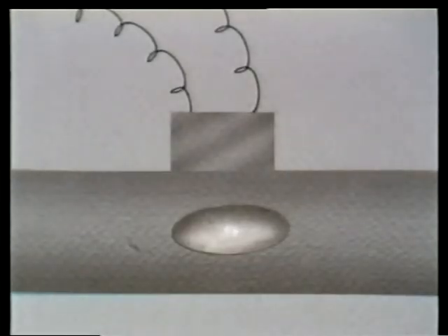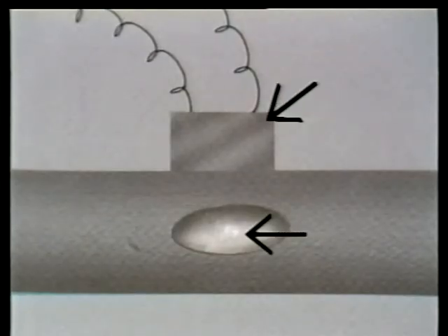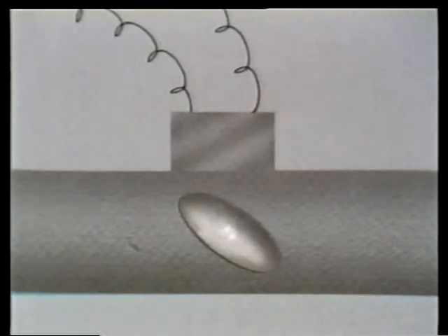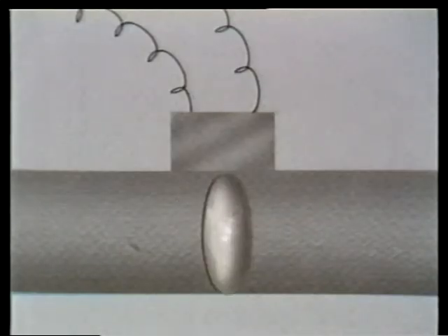The inlet air throttle is a butterfly valve within the inlet piping. The control unit up above receives a signal from the motor when it starts to draw too much current. The unit then partially closes the butterfly valve, restricting the intake airflow. If demand is still too great, the valve will close completely, effectively shutting down the compressor.